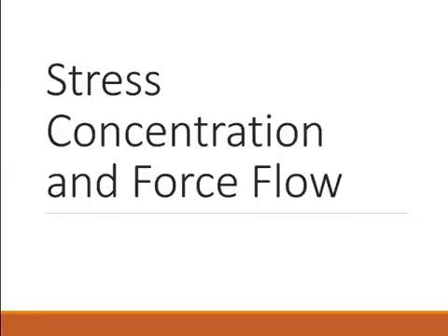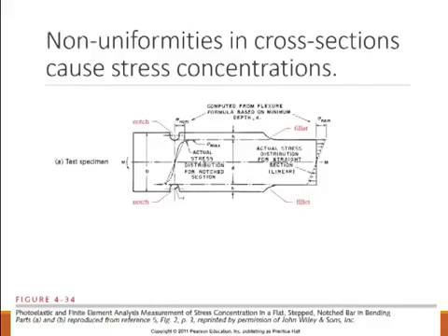In this lecture, we'll discuss stress concentrations and force flow through materials. When a part is loaded in a way that has stress concentrators, for instance, notches or fillets, not only do we see an increase in the stress because of a reduced cross-sectional area in this location, notice there's less cross-sectional area here than there is at this region, but we also see an increase in the stress because of the type of shape that it is.